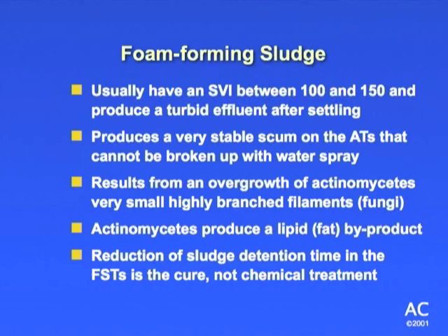What is that, Nocardia fungi? What's prevalent with that problem? Nocardia is one that's associated with the foaming sludge. Is that caused though by the fat, the grease? Yeah, it is. That's what it is. Yeah, the greasy stuff, because it's basically breaking down, and you're getting the lipid byproducts from the actinomycetes forming it.